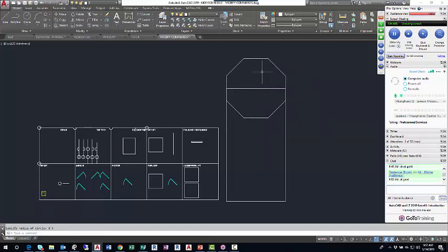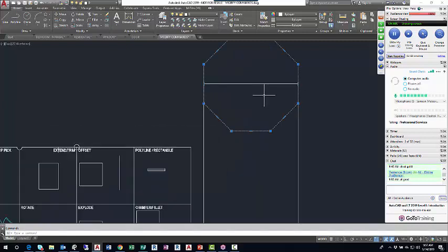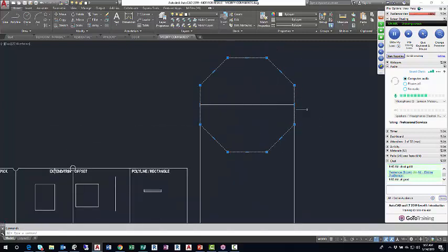That's the polygon. I used 8 feet 3 because the top edge of the rectangle was 16 feet 6. So 16 feet 6 divided by 2 is 8 feet 3. So I just wanted to show you that when you're using that circumscribe method, the long angle of your polygon will come to rest on the outer portion of your radius value.